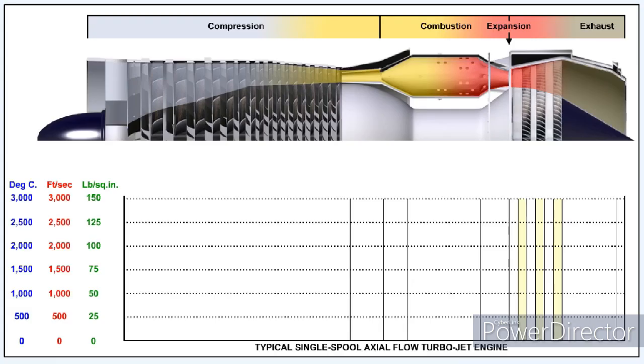The three main stages when these conditions change in the gas turbine engine are during compression, combustion, and expansion. During compression, work is done to increase the pressure and decrease the volume of the air. There is a corresponding rise in its temperature. Just as they do in the piston engine, higher compression ratios give higher thermal efficiency and lower specific fuel consumption.